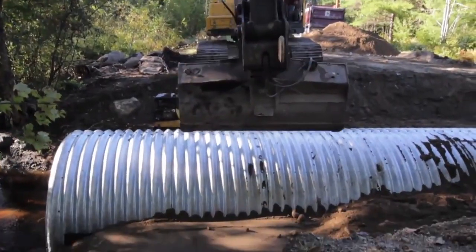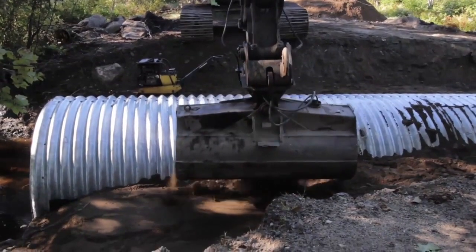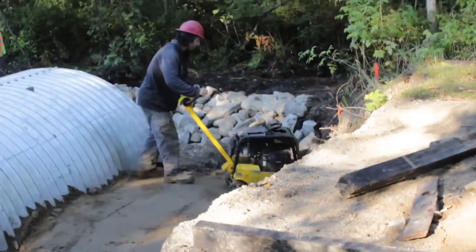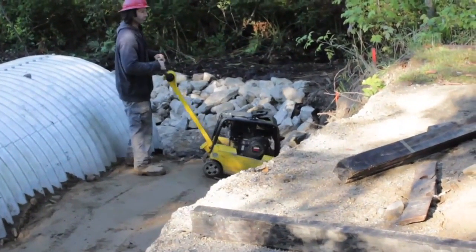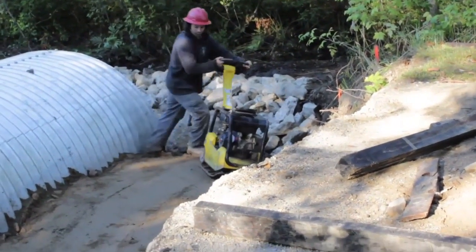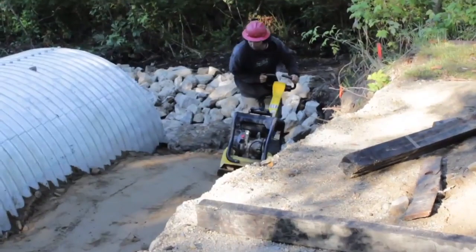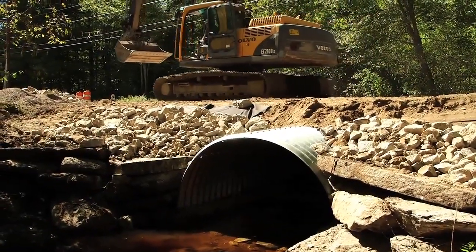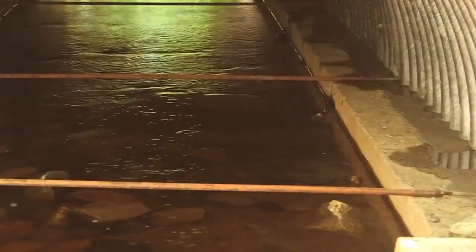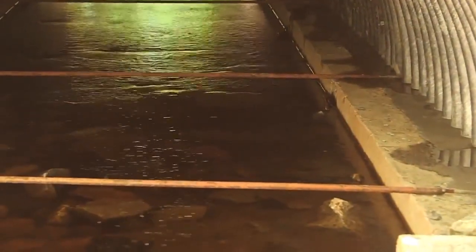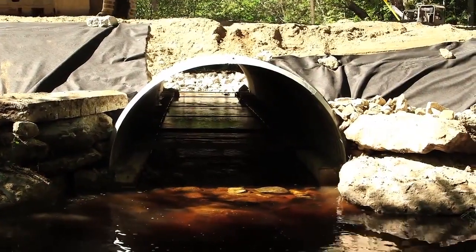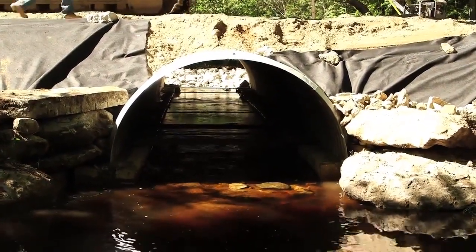The backfill next to the arch culvert is placed in 6 to 12-inch lifts that are mechanically compacted with a hand compactor, typically in an envelope area specified by the pipe supplier or as shown on the construction drawings. The raised concrete footings or knee walls for the arch extend 6 inches above the stream bottom to keep the metal out of the water during base flows, thus helping minimize long-term abrasion and corrosion.